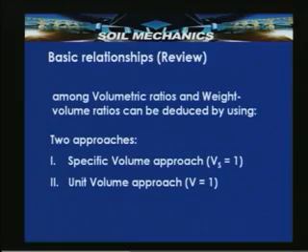If we review, we established different relationships among volumetric ratios and weight-volume ratios, and we also defined them in the previous lecture. And we said that there are two approaches in the phase diagram method. One is the specific volume approach, in which the volume of solids is set as 1, and the other is the unit volume approach, where the total volume is set as 1. So, in this lecture, let us look into the methodology of the unit volume approach.